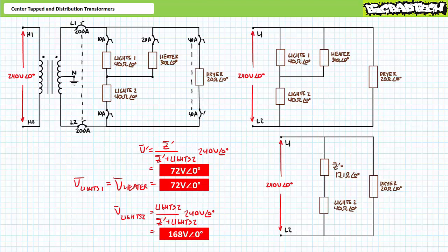It is for this reason one might observe odd behavior in a system lacking a neutral connection, such as unsteady lights flickering and dimming, or crazy motors surging and dying as loads are connected and disconnected. If you've ever had the misfortune of working on a house formerly owned by tweakers, as I have, be aware that those fixtures that they haven't stripped and sold for scrap metal most likely don't function as intended because they're not connected as intended. Again, not only does the neutral line in a split-phase system carry imbalance current in the event of load imbalance between phases, it also serves to ensure single-phase loads have access to a fixed potential.